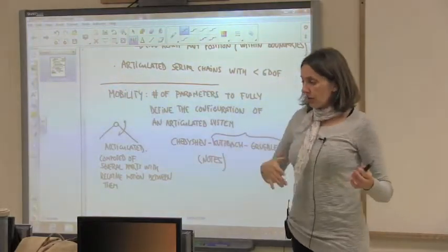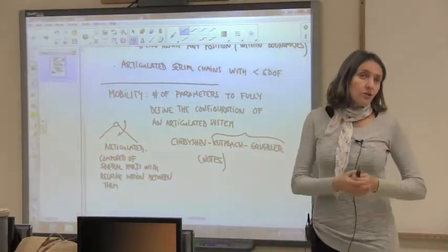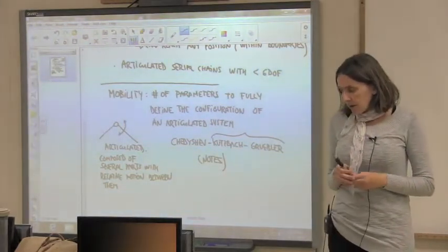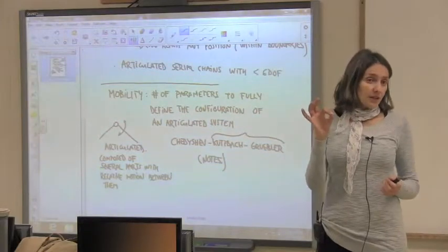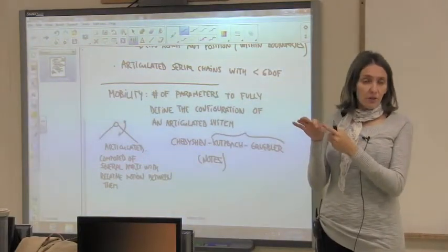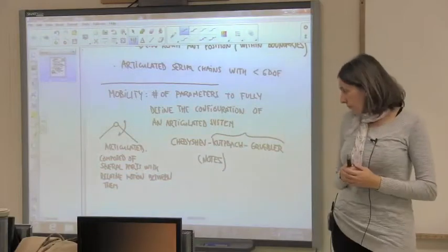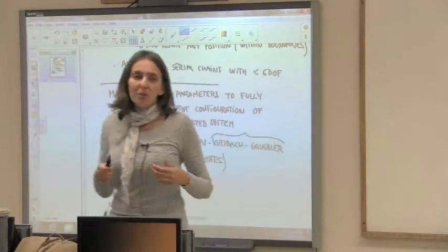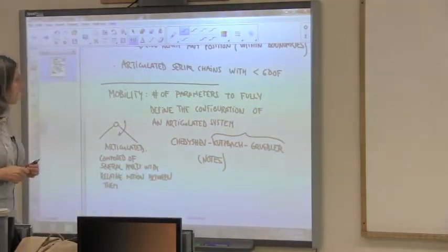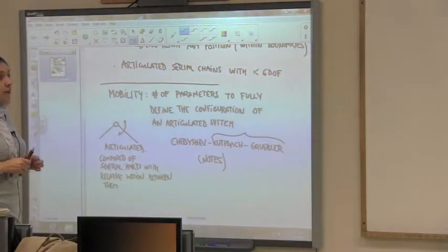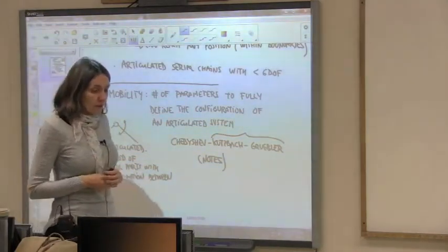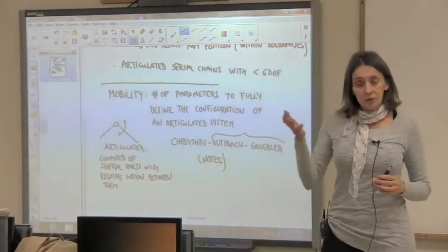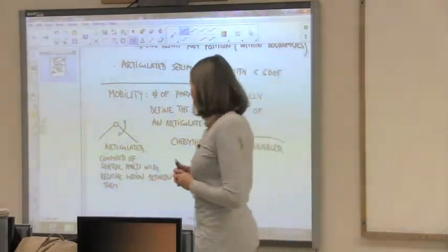I mean, we are used to the robot arm manipulators, and those usually have either 5 or 6 degrees of freedom or even more. But if you think about things such as fingers, usually you don't have 6 degrees of freedom in your finger, right? So those actually fall within what some people call robots with reduced mobility. Okay. Many parallel robots are also reduced mobility, so they are designed, for instance, just for performing orientations or just for performing translations.